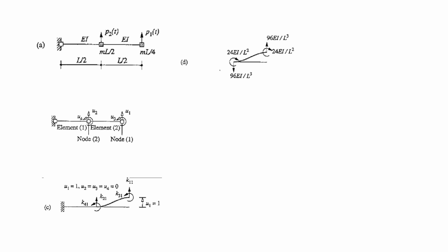Now where did we get this from? There are many methods you could use in order to determine this. The slope deflection method that you must have studied earlier, wherein you give a unit displacement and then obtain the other rotations and the deformations associated with it, the thetas and the deltas.